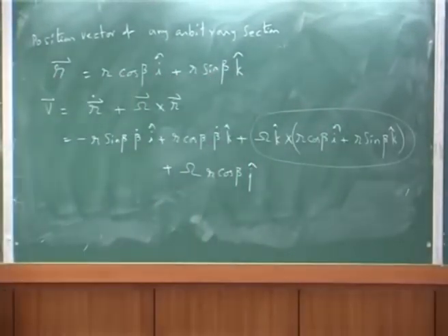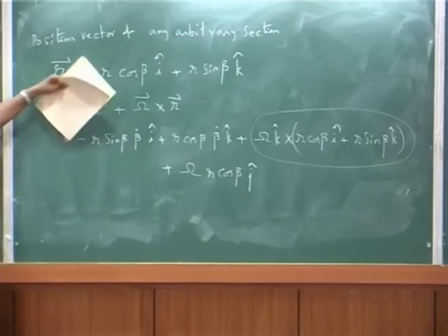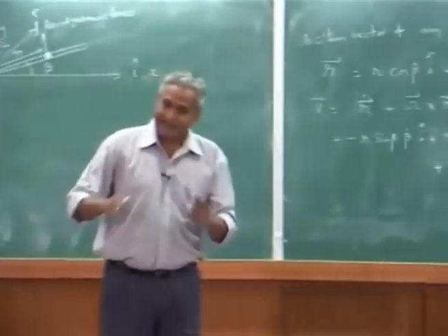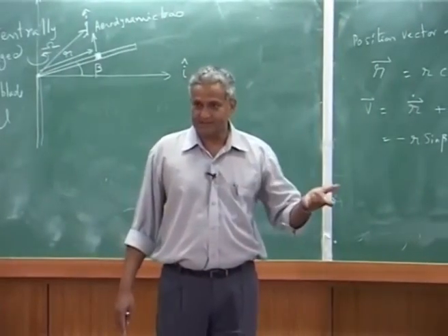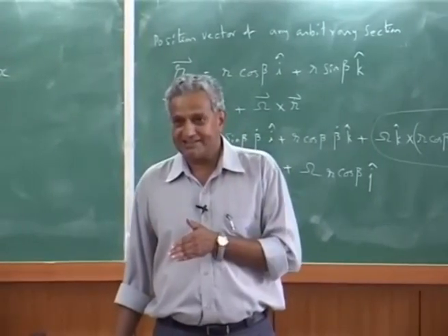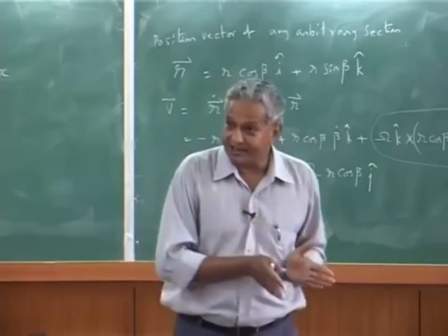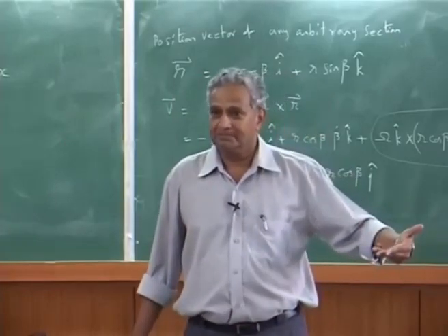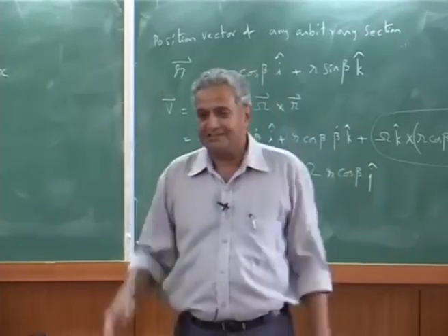This is my velocity. Then I go and get my acceleration of the same point. When I say acceleration, it is the absolute acceleration of a mass point attached to the blade, which is rotating. You can directly use that expression. Acceleration will have the relative acceleration, the Coriolis acceleration, the centripetal acceleration, and the angular acceleration. So you will have four terms. And then if your hub is moving, that acceleration also will come. That is how you develop the acceleration of any point.